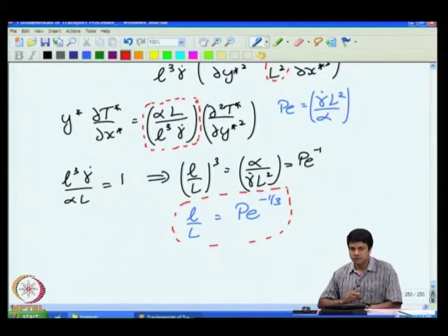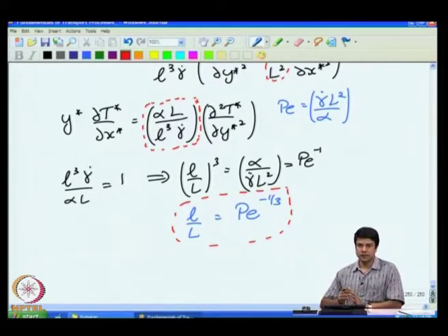That is because the transport from a surface cannot take place due to convection, because there is no velocity normal to the surface. Diffusion, on the other hand, is an isotropic process. It is due to the fluctuating velocities of the molecules, which have equal magnitudes in all directions, and therefore, they transport mass, momentum and energy equally in all directions. Therefore, very close to the surface, even though convection is not present, there is still diffusion, and that diffusion is what causes transport from the surface itself.